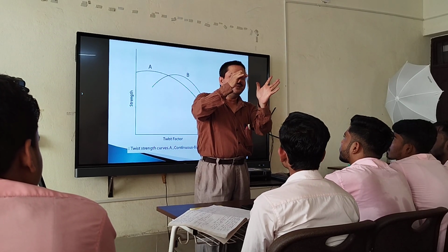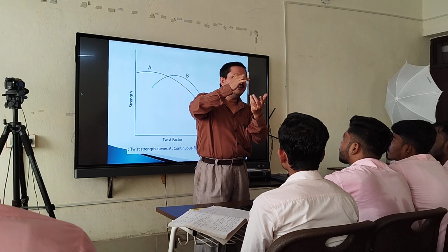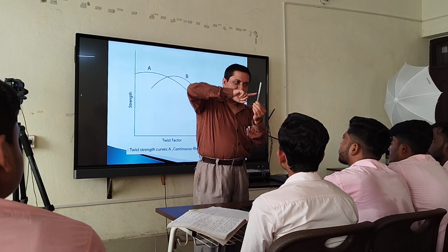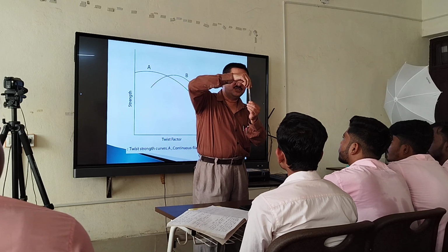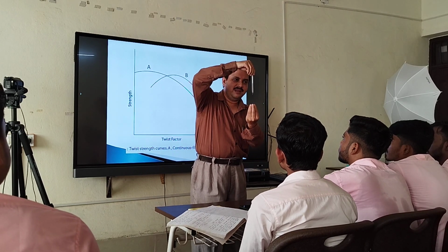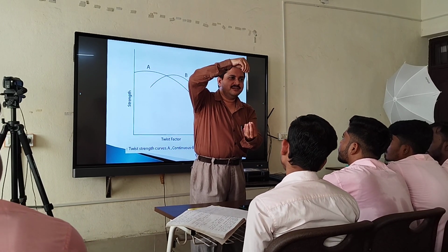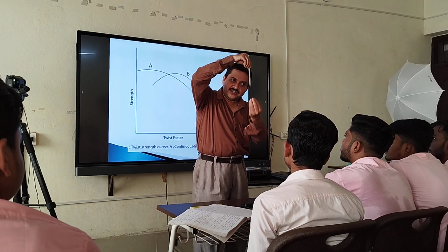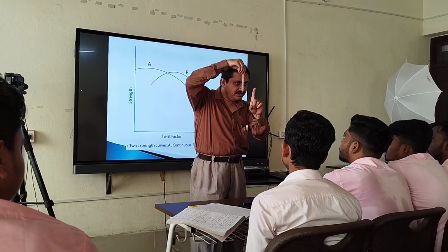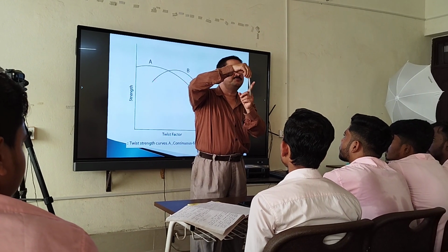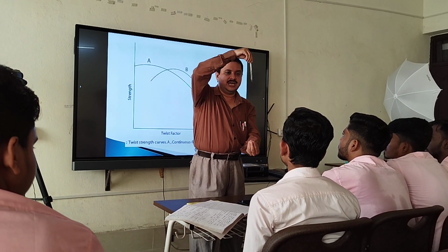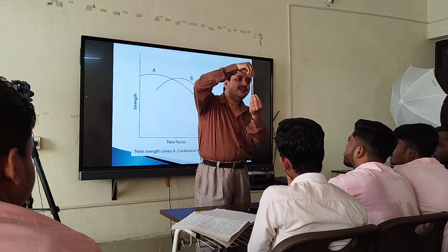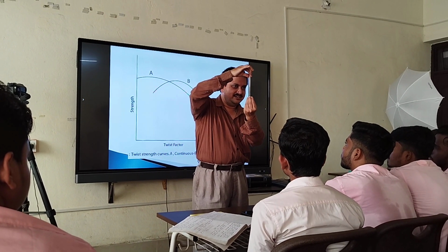As the fiber strands are spirally deposited, how much load are the fibers sharing? Not T amount, because they are not parallel to each other. So one component of the load, that is T cos theta amount of load, will be shared.